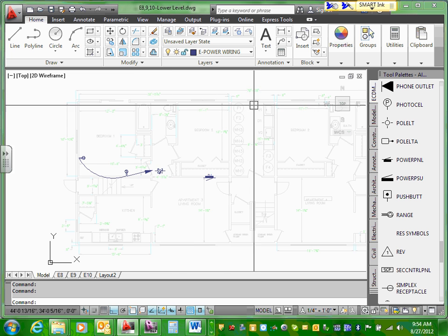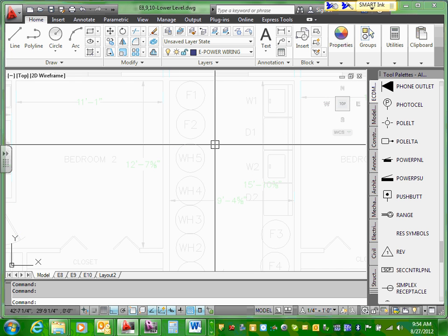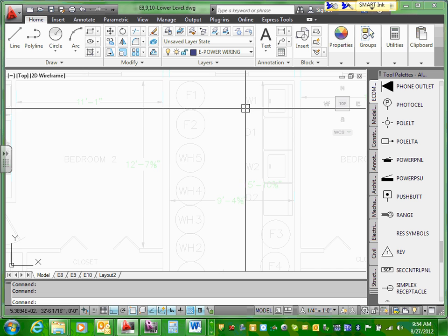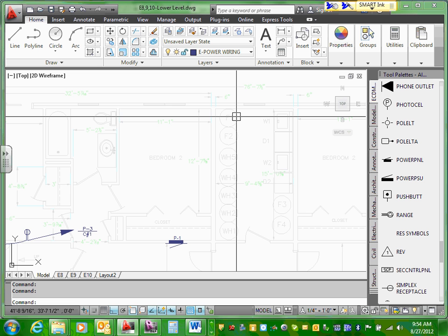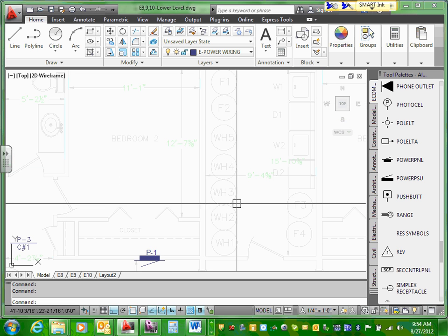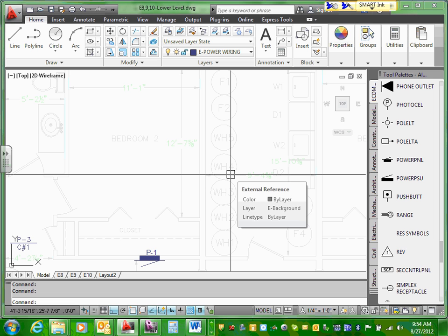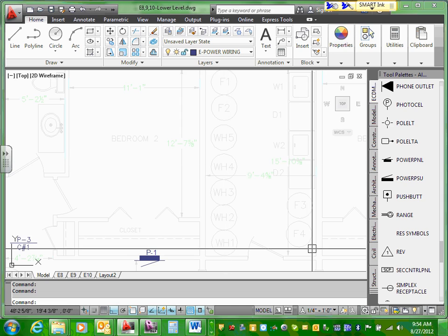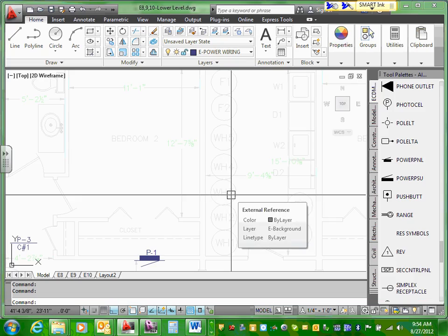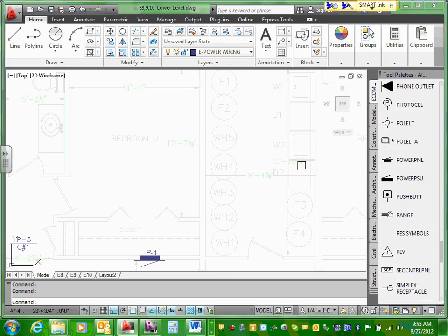I want to remind you that this area here is going to be very crowded. So you have to be very creative. Whoever is doing the bottom, this area here, it's going to have each furnace with its own dedicated circuit, 15 amp by code. Each water heater here is going to have its own dedicated circuit, and it's going to be 30 amps. Each one of these has to have its disconnect by code right next to it. The furnaces will be snap switch. The dishwasher will be an actual disconnect when you guys go there.